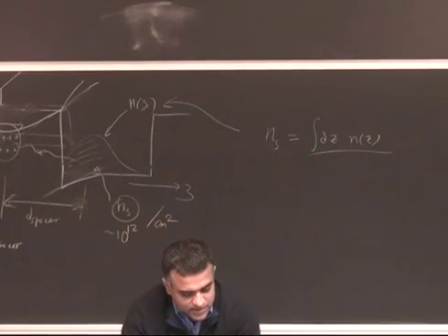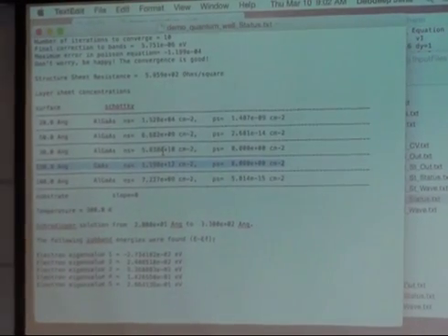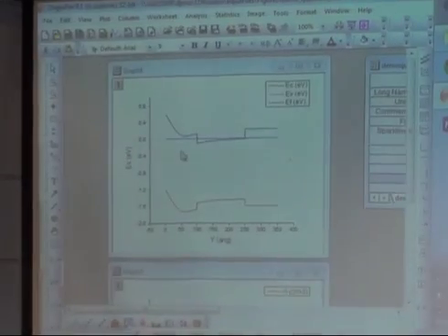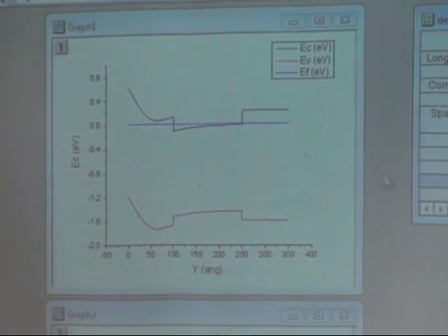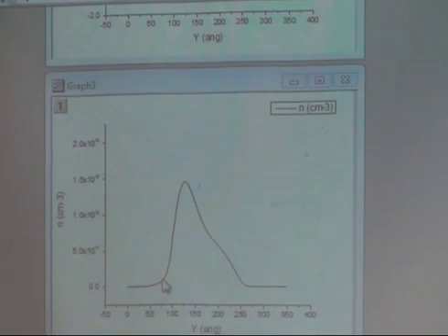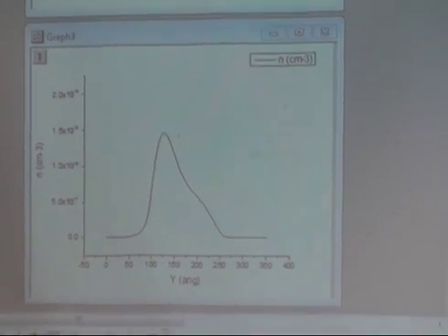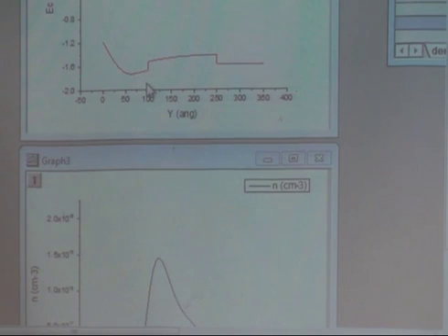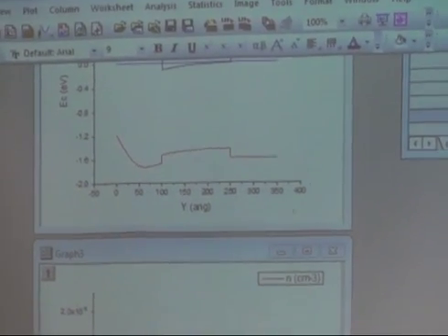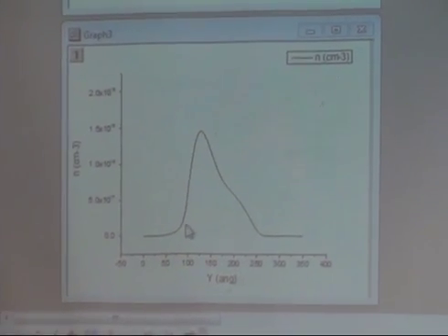It's integrated over this thickness in the quantum well, but what you also see here is that there are some electrons in the barrier. I think you realize this is because it is a finite barrier, and there is a penetration of the electron wave function. Though the barrier is sharp at 100 angstrom, the electron gas spreads out. It's not limited to 100 angstrom. There's a tail there.